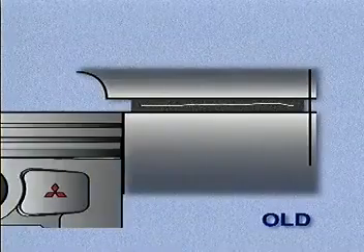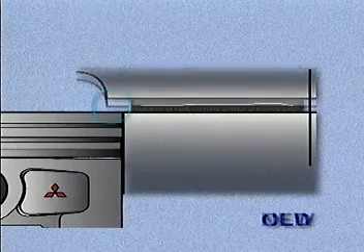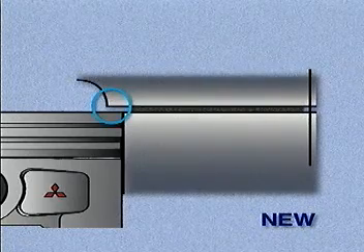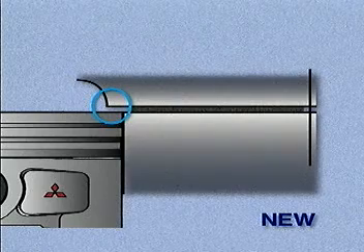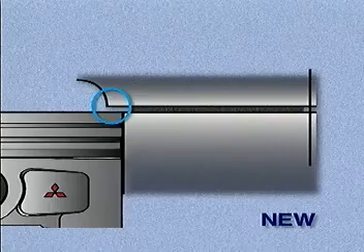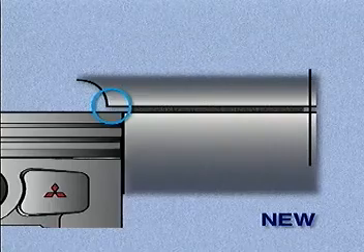And a new cylinder head gasket is used on both engines. The gasket has been changed from a carbon material to a multi-layered metal gasket. This design decreases the volume of unburned gases trapped between the cylinder block and the cylinder head, resulting in less unburned hydrocarbons in the exhaust.